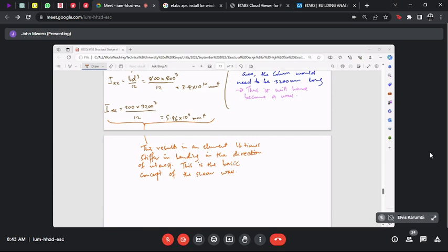Now, as you change the form of the structure, two things are changing. One, where ideally you can assume lumped masses changes. Two, the stiffnesses connecting those lumped masses also change. And as you are aware from your third year dynamics of structures, I think, if you change any of the parameters of the system, the period of vibration changes.